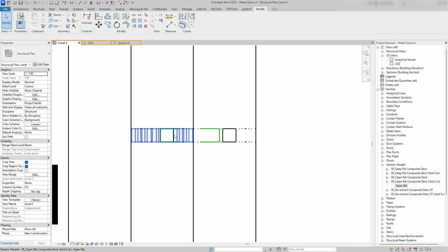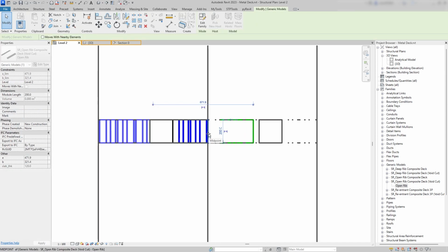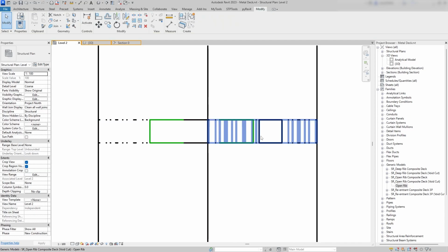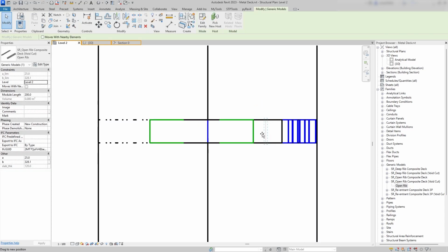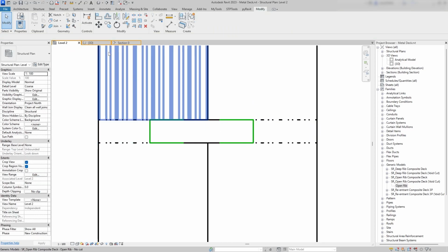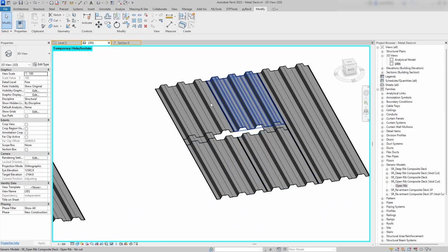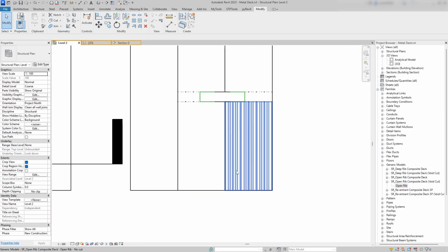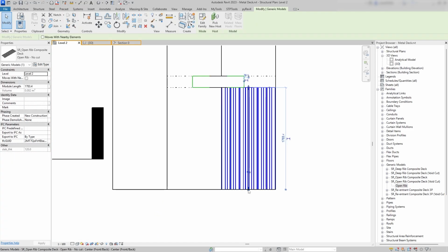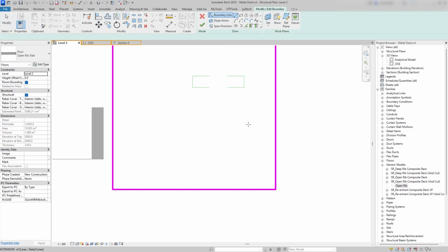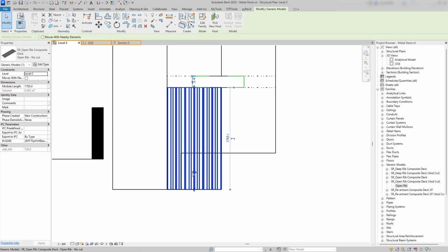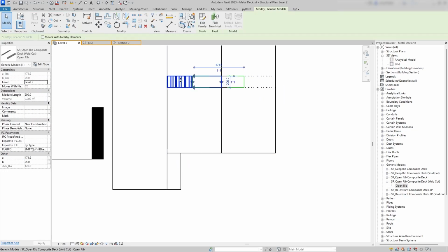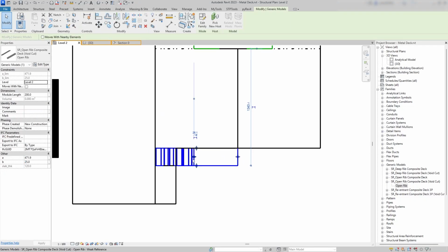Here we can take the sheet on this side and extend the cut to the slab edge, while extending the cut on the other sheet to this end. This way, the two cuts work together. Finally, if the opening is larger, say for a staircase, it makes sense to modify the slab boundary itself. We can also use the void cut version of the family to make adjustments where the opening overlaps with the staircase area.